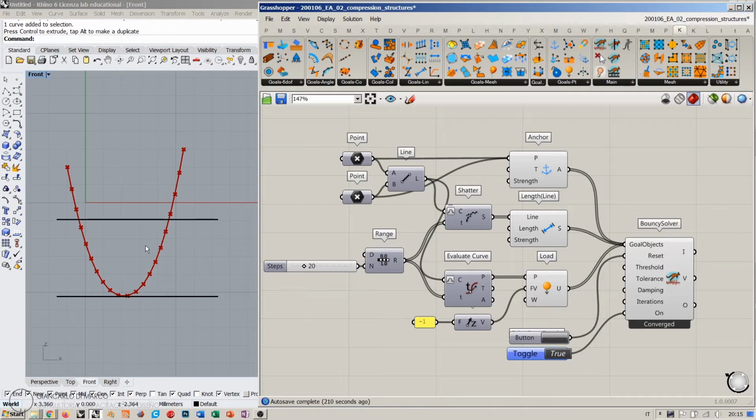So once you understand this, you are capable of creating a well-proportioned architectural body here in Rhino. Now, let's switch to Grasshopper. Gravity is not -1. Gravity is -9.81 eventually. Okay, so this parameter here, this value here must be set to the proper value for gravity. Okay, but the more important thing is elastic force. Okay, so basically, elastic force takes into account what material we are using in our simulation.